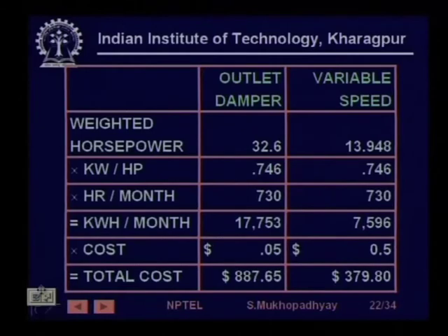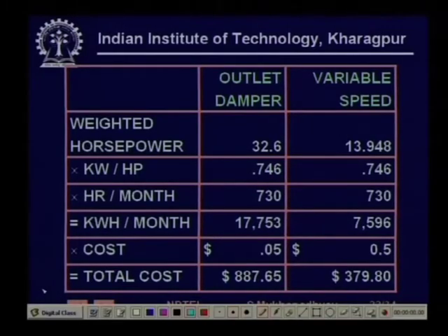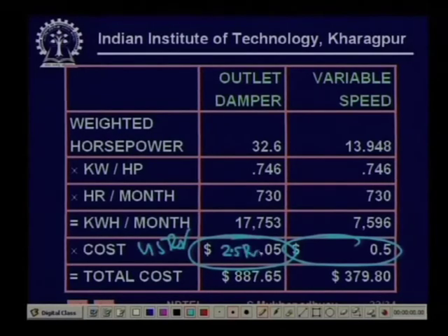This is a little calculation, this dollar figure is because of the source from which this is taken, but this turns out to be almost equivalent in rupees. If you take about 45 rupees per dollar, this becomes about 2.5 rupees, which is an average rate, not exact, it varies from state to state, it varies on various energy slabs, and industrial energy rates do not depend just on the kilowatt, they also depend on the maximum demand.